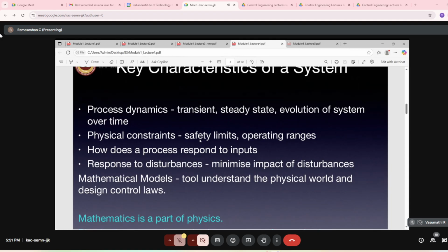Okay. So time invariance mathematically means if you give the input after 100 years, you get the same output as you get now with the same input, except that it will also be after 100 years. Got it? Yes, sir. So if u of t gives y of t, then if you give u of t minus 100, the output will be y of t minus 100, the same y but shifted by 100. So if that happens for all delays, whether it is 100 or 200 or 1000, then it is a time invariant system.